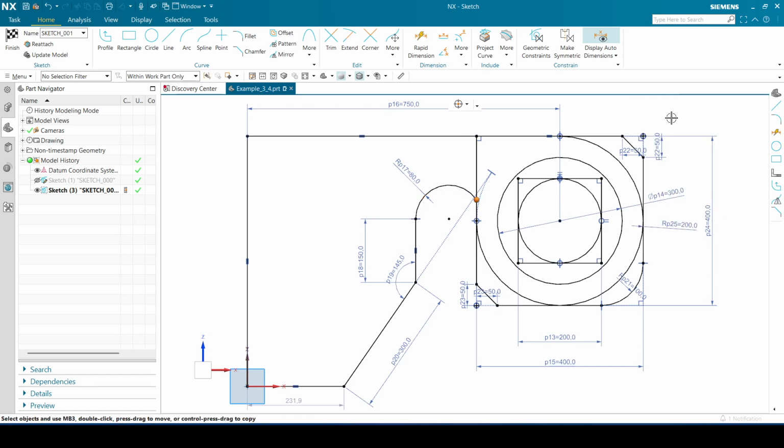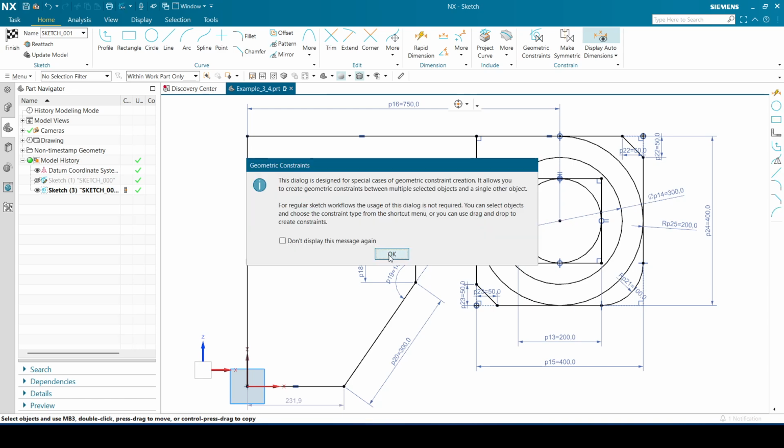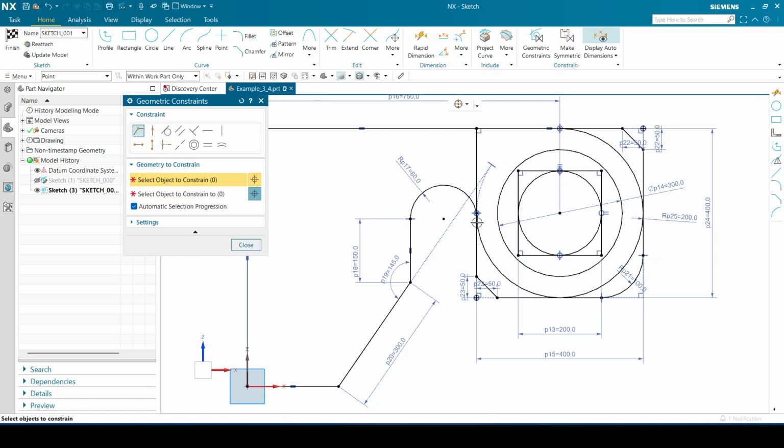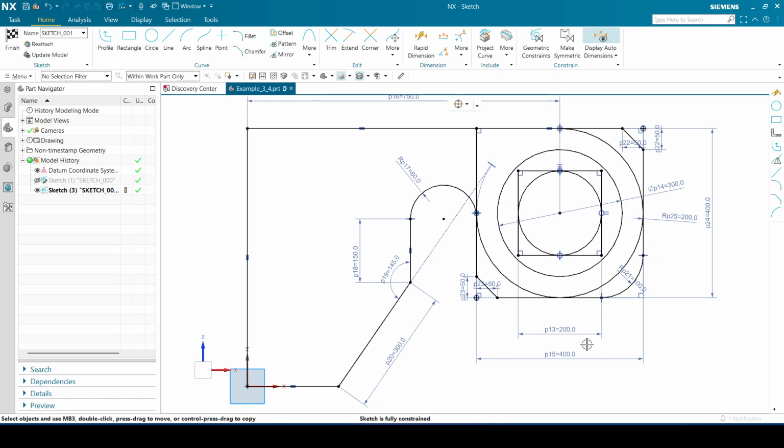So now we can just connect these 2 points to one another, because this is in the center of here to here, because it is tangent. So I'm just going to click C to go to my constraints. So I want coincident, so that they are in the same point. And there we go. Now it's fully constrained and we have all these features. So the important part is to stay calm when stuff looks like it starts to break, and just go through it methodically. And if you do something and NX freezes, rather not do that again.